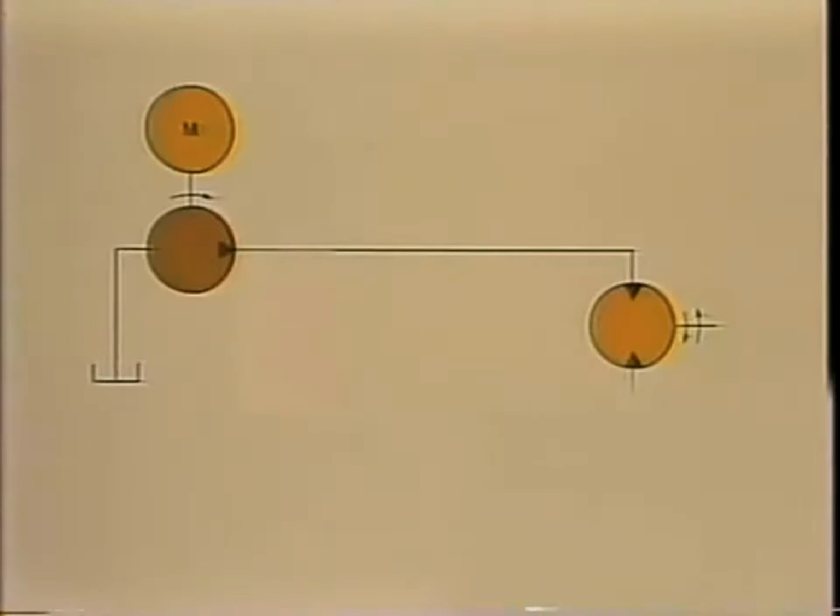Now, with an electric motor driving our pump, let's see what happens with our hydraulic motor. Since it's a positive displacement unit, if it were to stall, it could not accept any more oil. The pump, also positive displacement, would stall too, since its outlet would be blocked. This in turn would stall our electric motor.